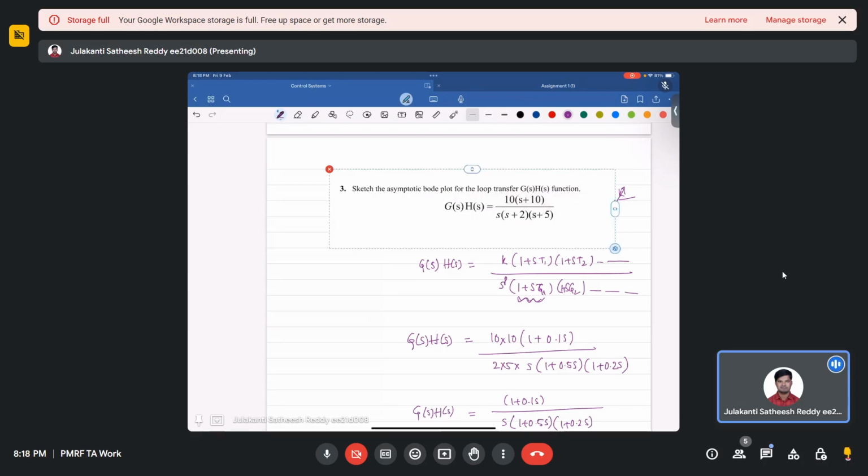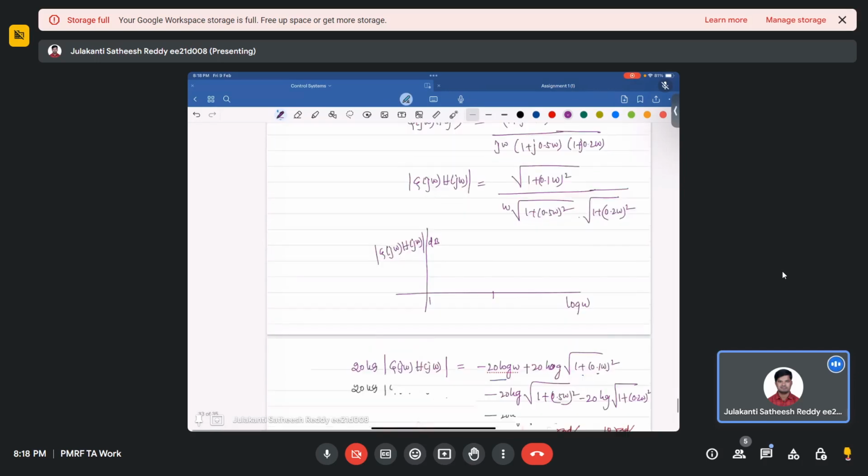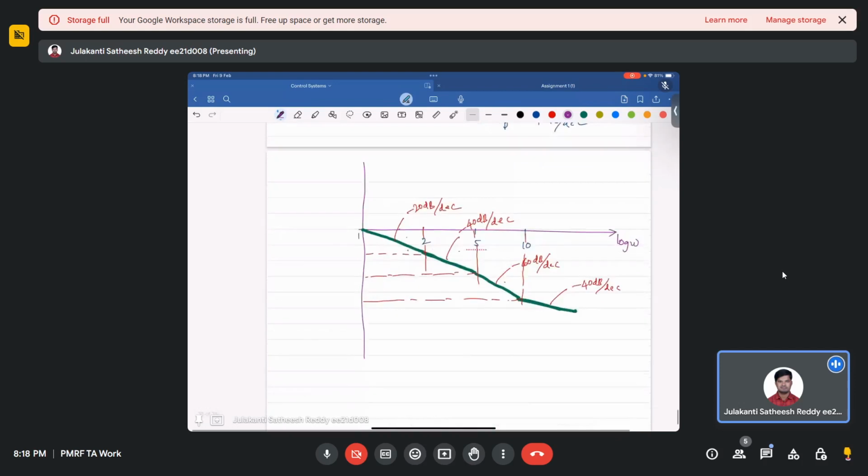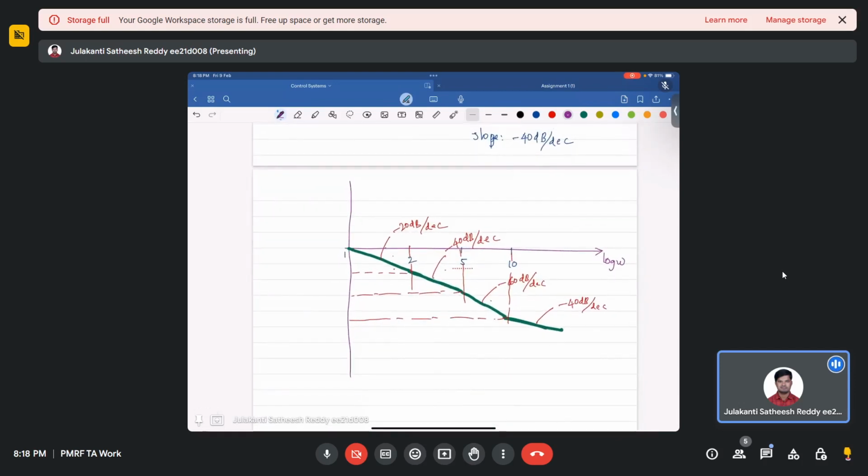If you multiply those two, then you will have that, right? So by varying what parameters, how the system is going to behave, whether it's first order, second order, or third order. Okay. So now the best way to bring the system function is always first order: design a controller in such a way that the system has only a first order response in that frequency region. So that the bandwidth of the system will be a little higher. This is where the Bode plot helps a lot. You can say the best way of designing the controller is the Bode plot.